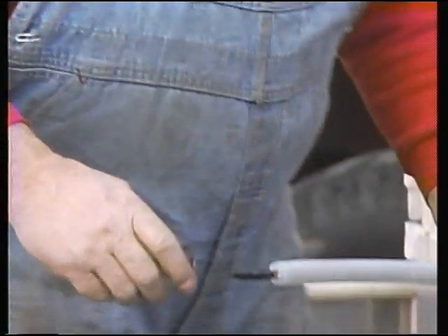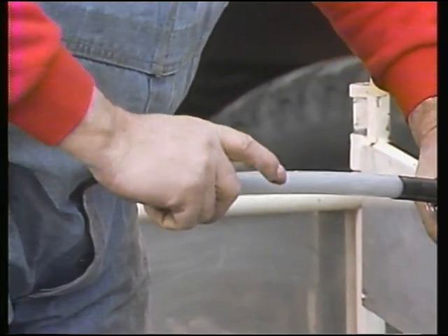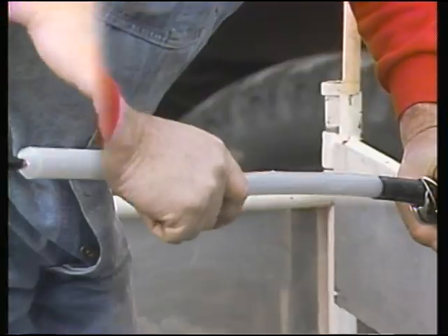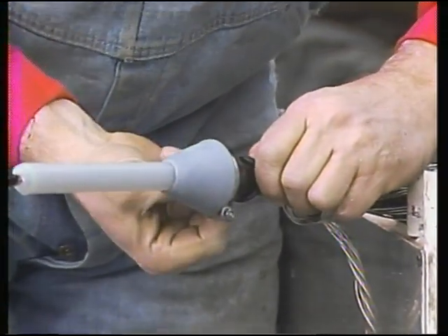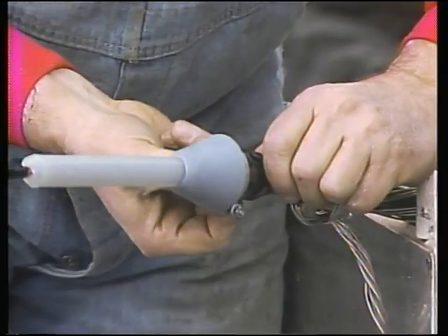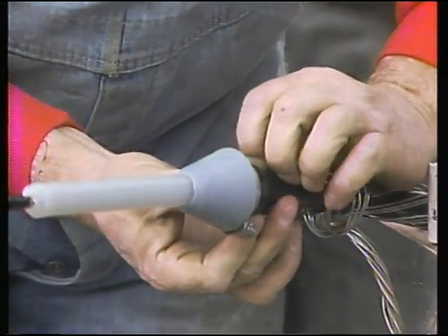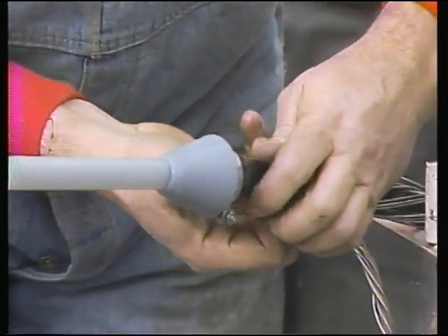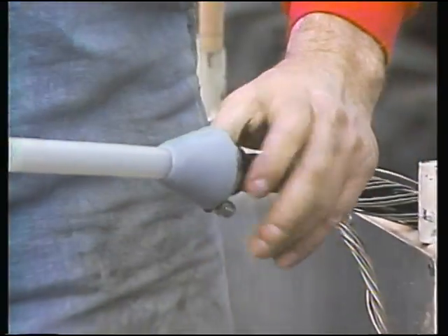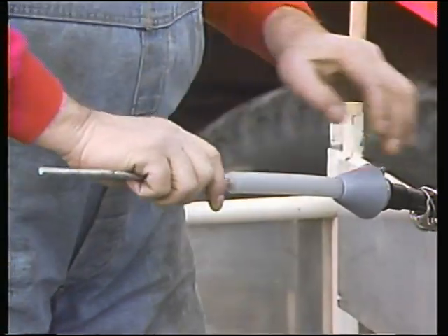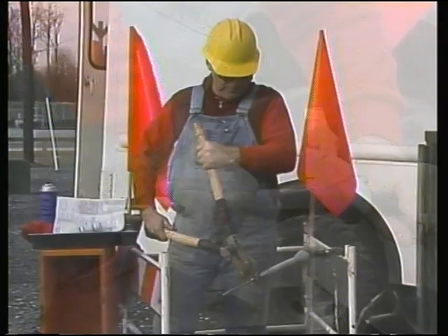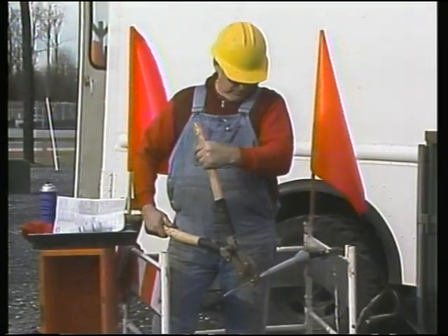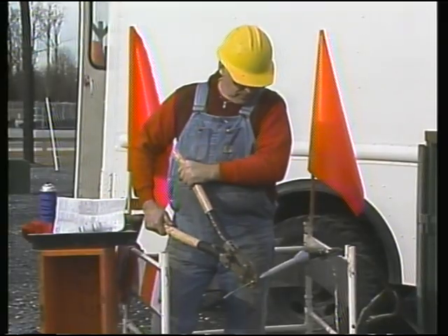With the silicone grease on the insulation, he slips the cone onto the cable. Then he positions the end of the cone so that it butts up against the semiconductive insulation shield. He then unrolls the end to overlap the insulation shield layer. After removing the protective tape, the workman installs the connector. He crimps the connector onto the conductor according to the termination instructions.